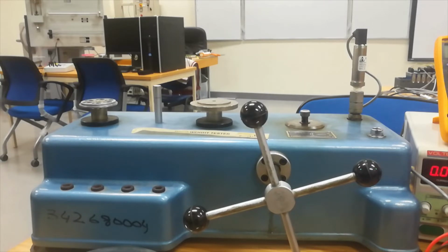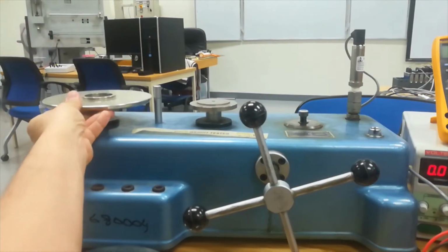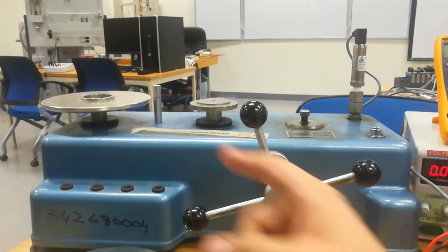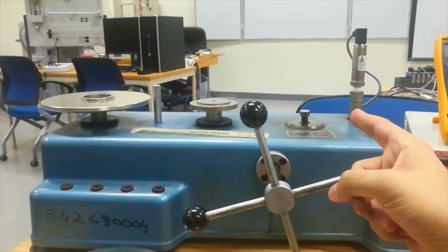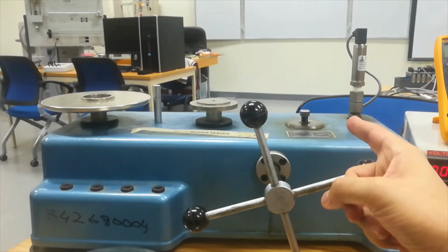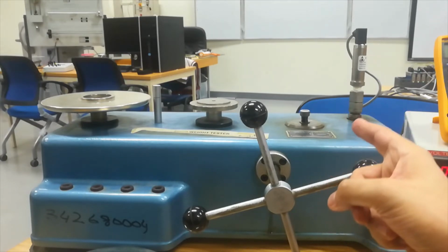If you want to apply pressure, you need to make sure that all the oil points inside the tank have the same pressure. And to make sure of that, you need to be sure that there is no point for the oil to escape when you apply this pressure. So if you apply any weight, you are expecting that the pressure coming from this weight will be reflected on this pressure transducer, under the condition that the oil does not have any place to escape to.